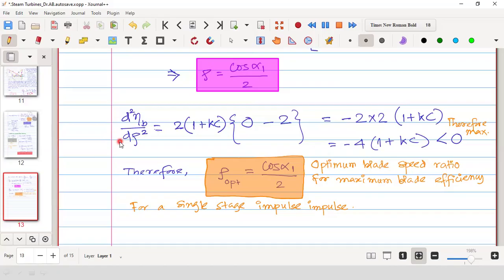Also at the exit there will be high carryover loss. So it is not wise to use a single stage expansion, because that is not economical, and also in terms of the technical things, that is not possible to control.